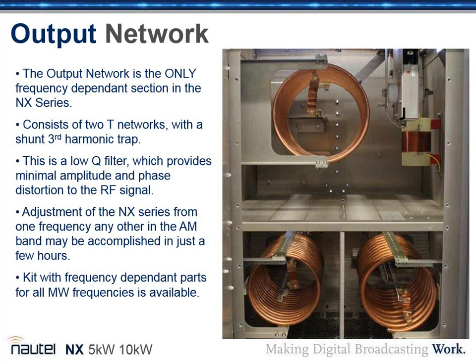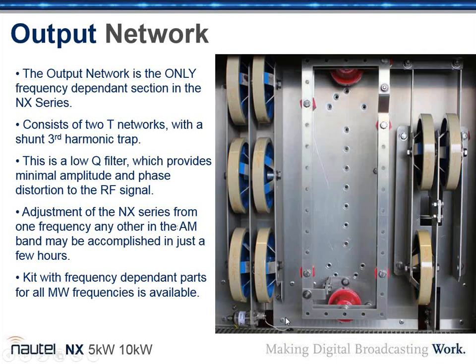Exactly. Okay, excellent. And on the back side, this is where the capacitors go. So these are the 2 capacitor banks that are part of the 2T networks of the filter. And then the strap in the middle is the third harmonic notch. So this strap here is actually an inductor. Yes. And as we change the frequency of the transmitter, the position of that little thing right there changes, perhaps. Exactly. Essentially, it's supposed to resonate with that second capacitor bank at the third harmonic frequency.